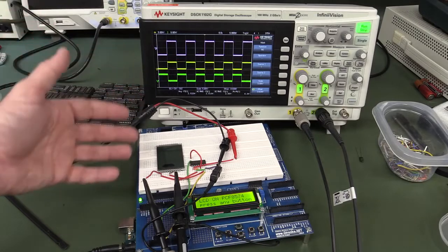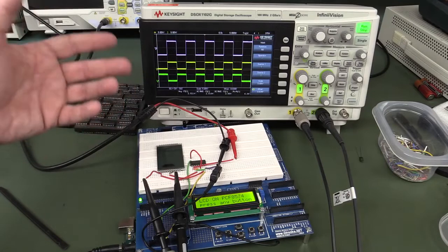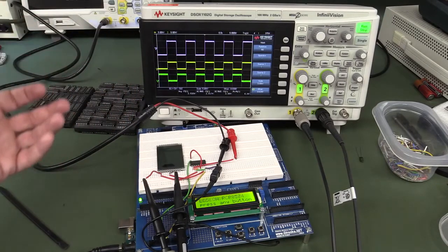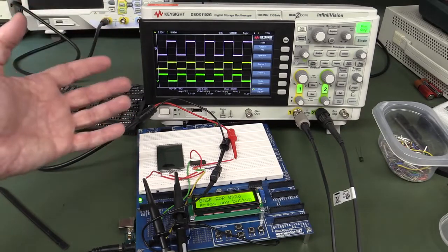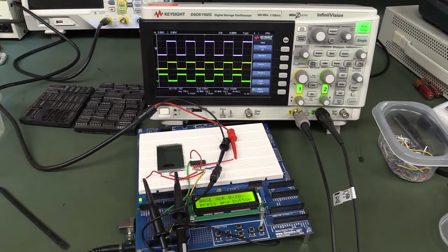Once you go to multiplex, you can do it with a microcontroller and discrete logic, but it just gets a bit harder because you have different bias levels and things like that. And in that case, for multiplex ones, I'd recommend going to a proper LCD driver chip or a microcontroller that has a proper LCD driver built in.